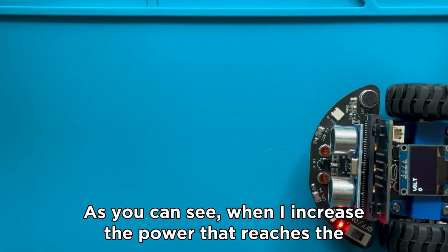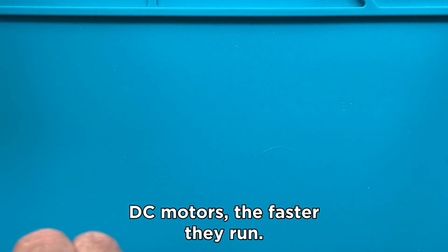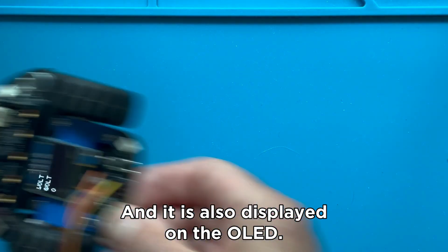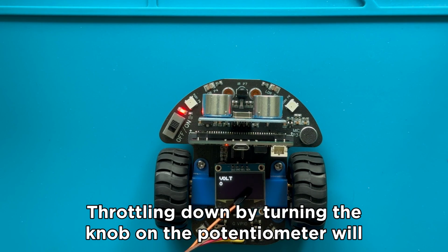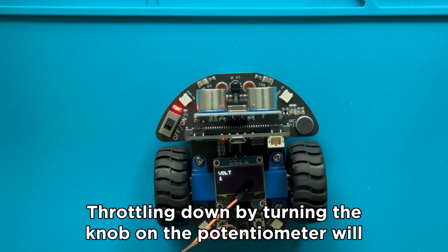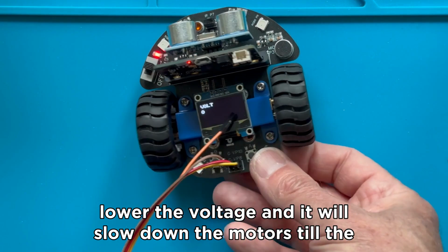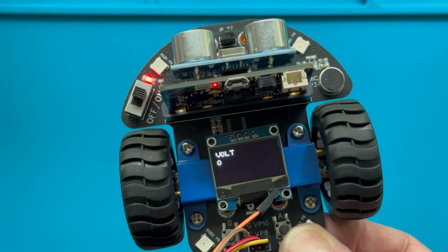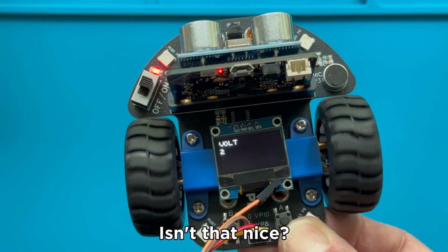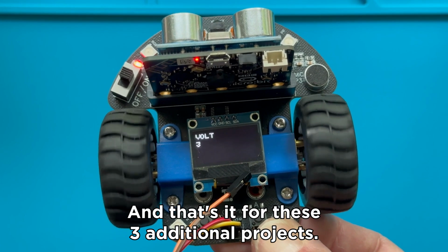And as you can see, when I increase the power that reaches the DC motors, the faster they run, and it is also displayed on the OLED. Throttling down by turning the knob on the potentiometer will lower the voltage, and it will slow down the motors till the microcar stops. Isn't that nice? And that's it for these 3 additional projects.